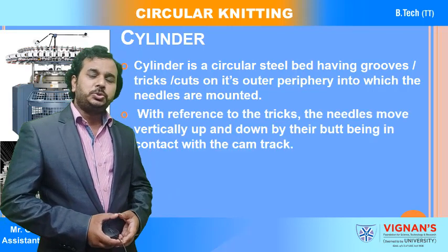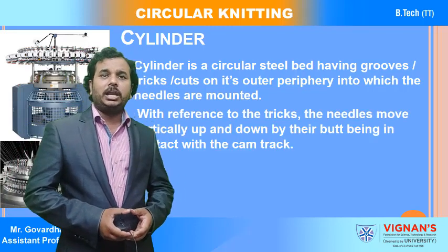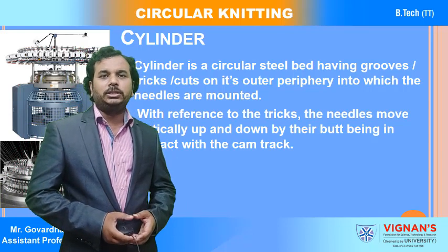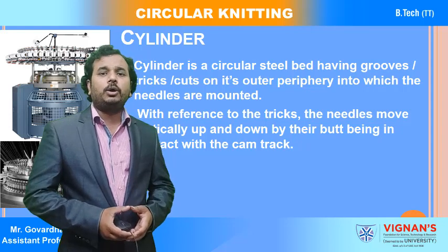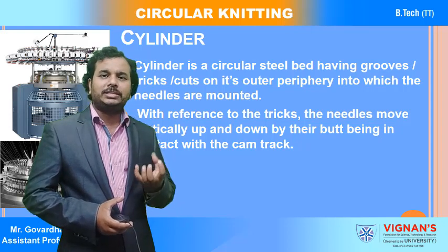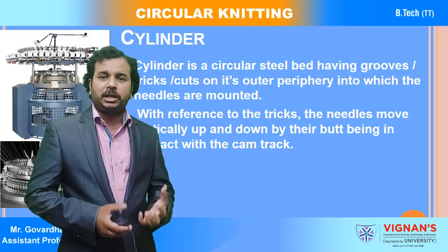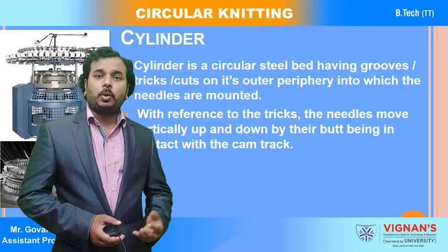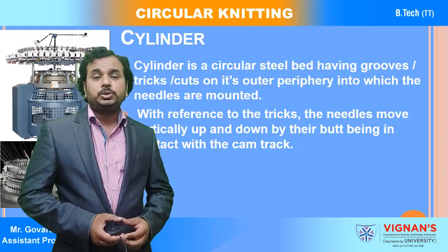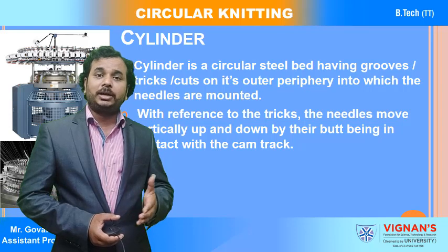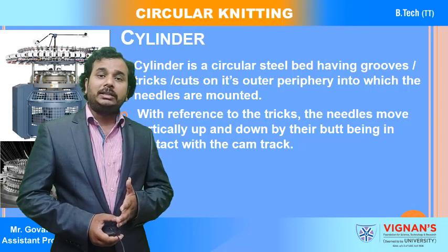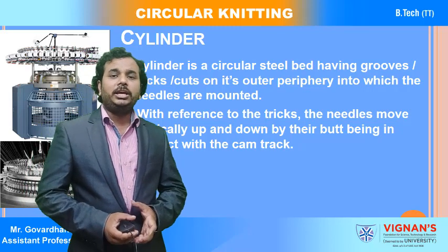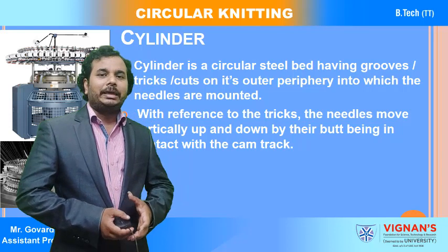With reference to the tricks, the needles move vertically up and down, as I told earlier. Their butts follow the cam tracks. Now the cylinder is rotating, and on the outer periphery of the cylinder we have the needles. The needle butts are projected outside the periphery of the cylinder, and the cams are fixed to engage the needle butts. So the needle butts follow the cam track.